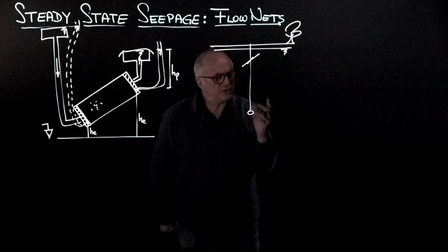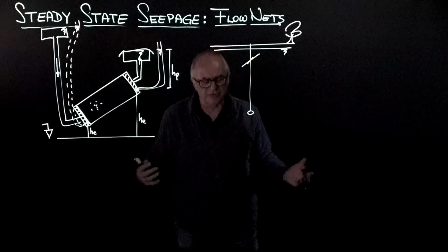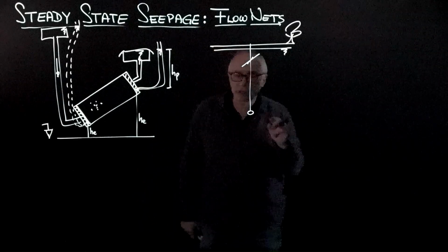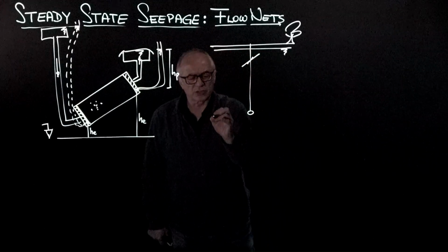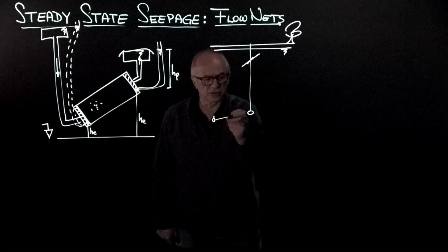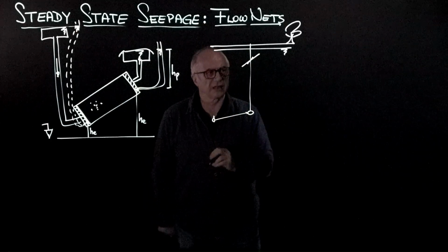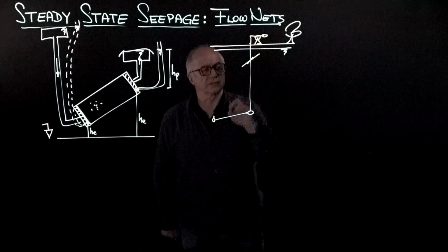And so what is my first equipotential, my last equipotential, the boundary flow lines? It gets very tricky. But if you think as a water molecule, then you say, well, I will go from here to the location where I am pumping, where I'm pumping the water.